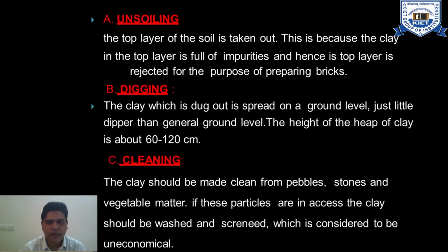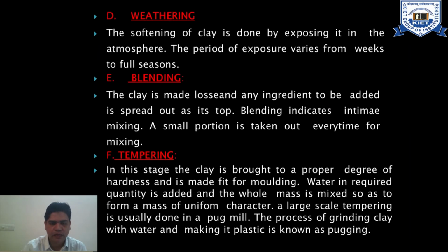Cleaning. The clay should be made free from pebbles, stones and vegetation, that is, organic as well as inorganic impurities. If these particles are in excess, the clay should be washed and screened, which is considered to be uneconomical. Weathering. The softening of the clay is done by exposing it to the atmosphere. The period of exposure varies from weeks to a full season.